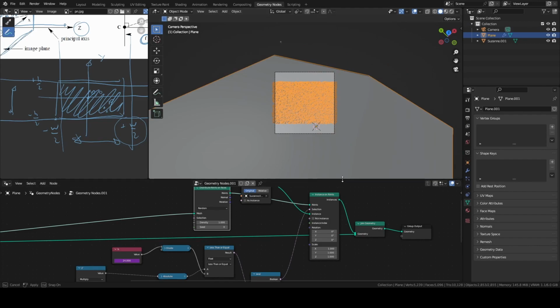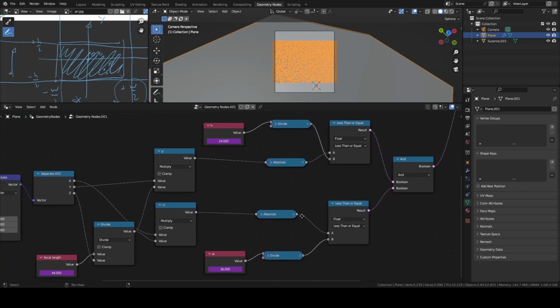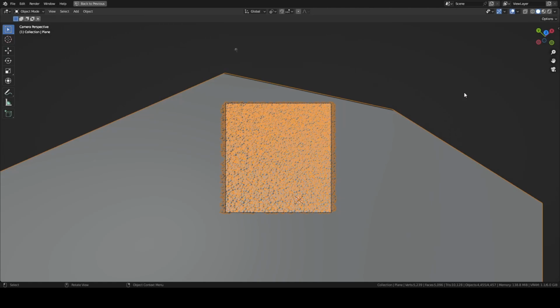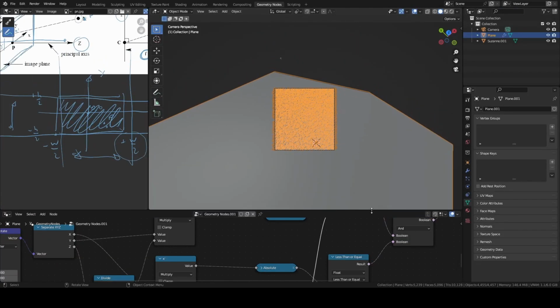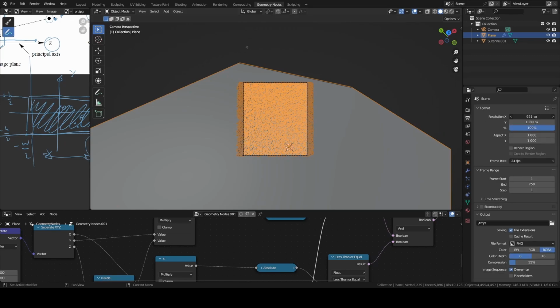And in my opinion, the easiest way to solve the problem is to take those two parameters, H and W, which are the sensor size, and get rid of the smaller one. So let's take this H and delete it and use instead my W divided by 2. What we are doing here is to create some more points than needed usually.